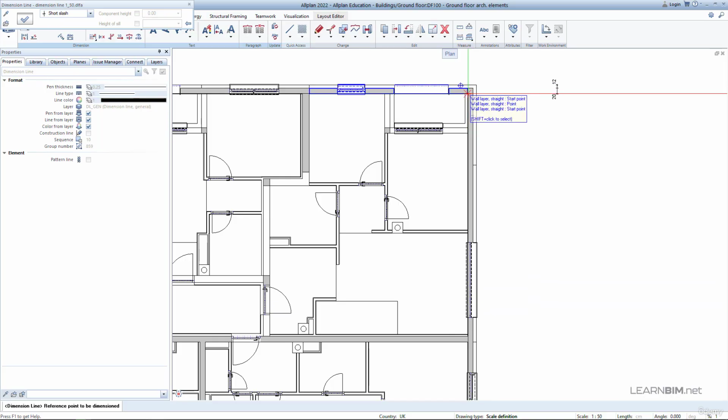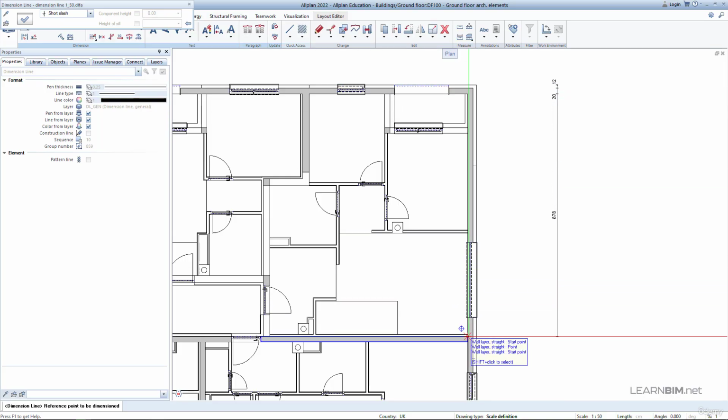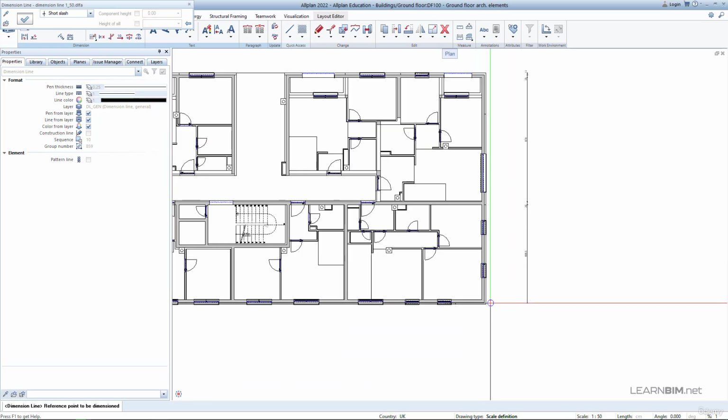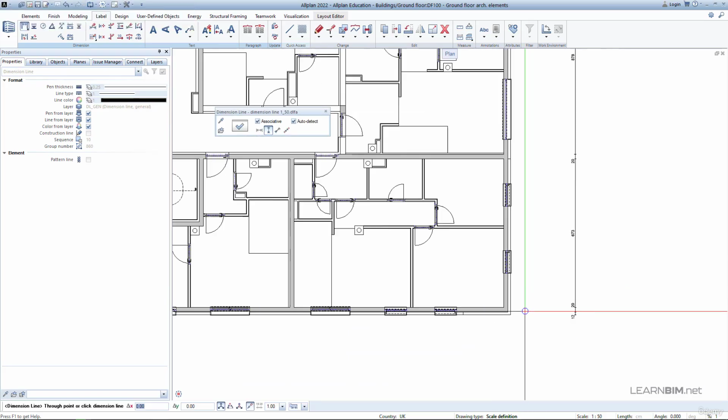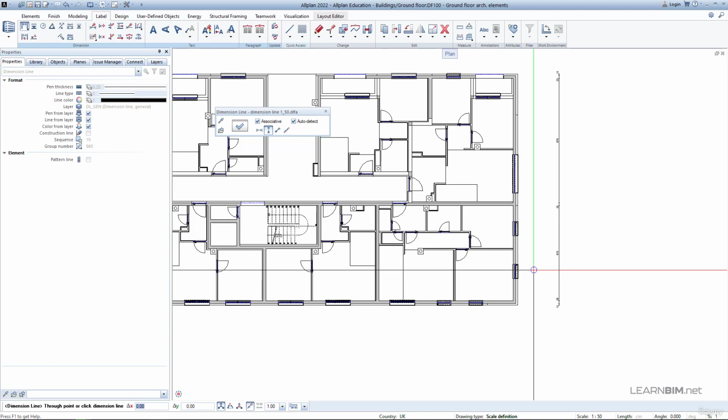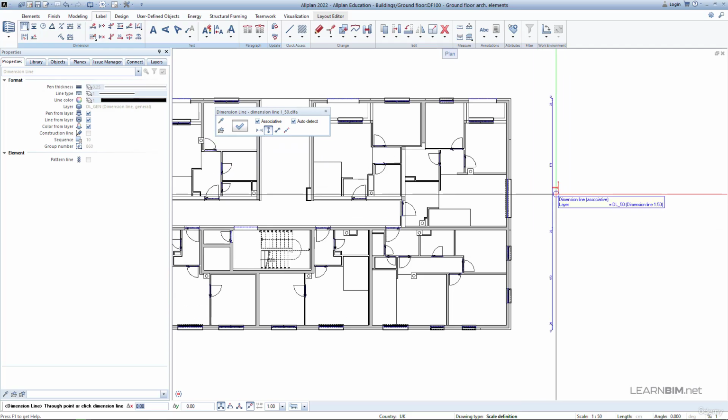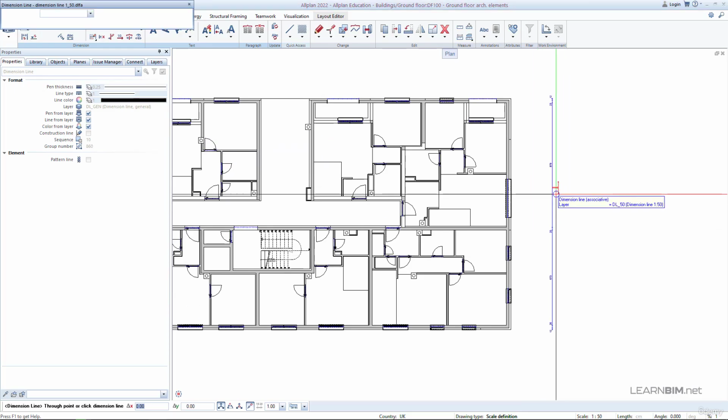On first dimension line, you can dimension the insulation and walls. When you are done with dimensioning, click the Escape key for ending the drawing of the first dimension line. For defining the second dimension line, first you need to define the direction of the 9 mm offset between the dimension lines. Approach the first dimension line and wait for red arrow to appear. Then confirm the position of the second dimension line with the left mouse click.